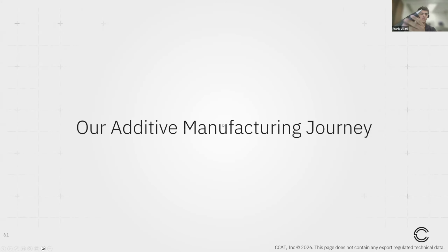So to start with the nose cone, I was able to use one of our metal additive processes to print this nose cone tip out of Inconel 625. It's completely overkill for this project. However, it is a material commonly referred to as a superalloy. It is an incredibly high temperature metal that can resist deformation. I know a lot of jet engine manufacturers utilize it for their impellers.